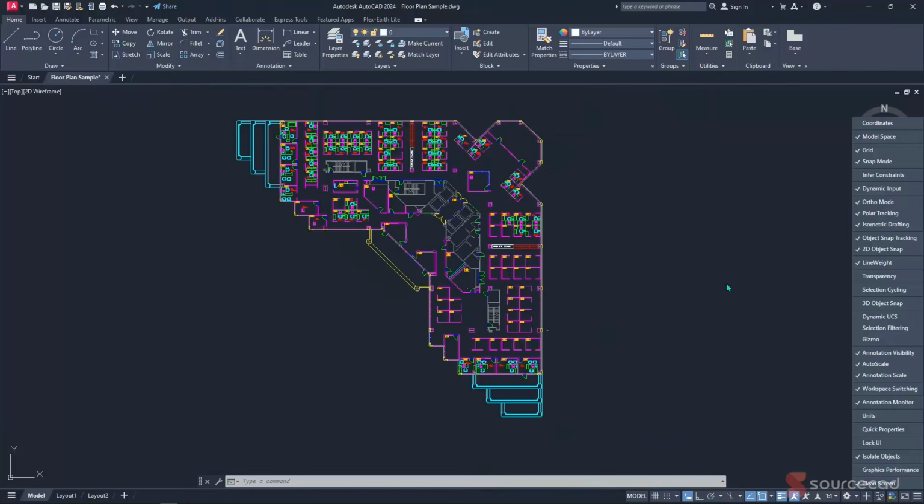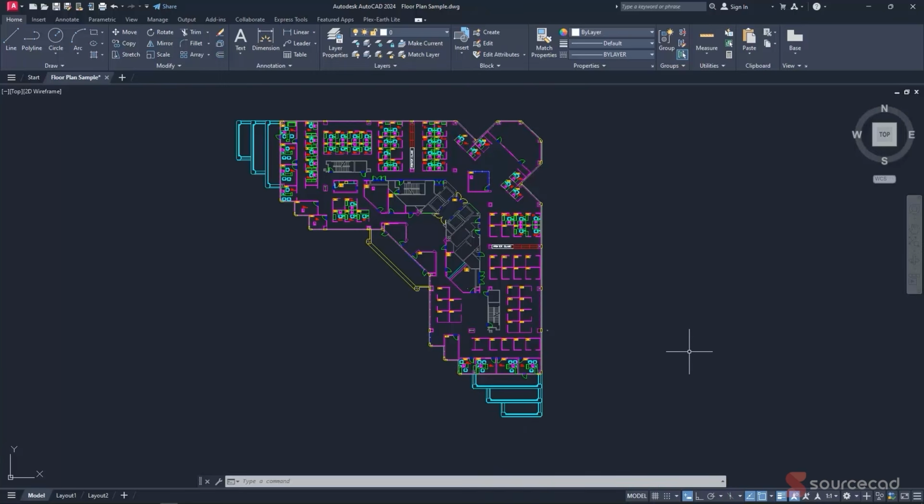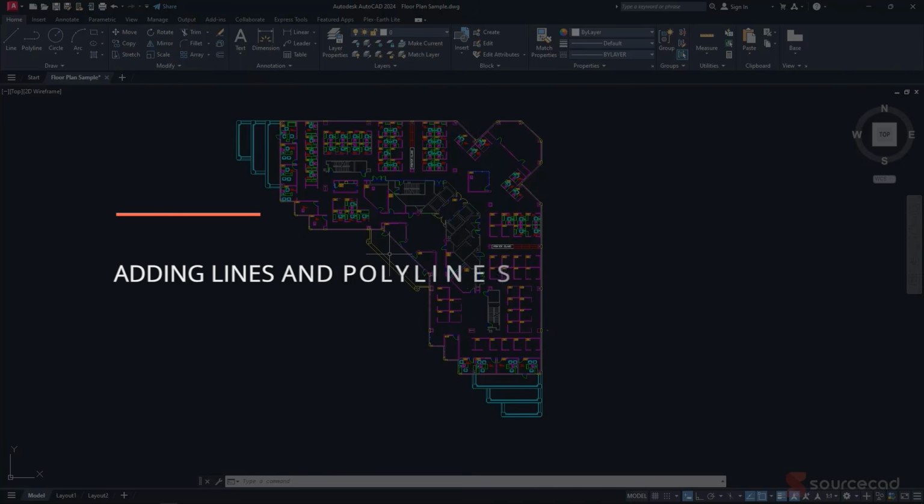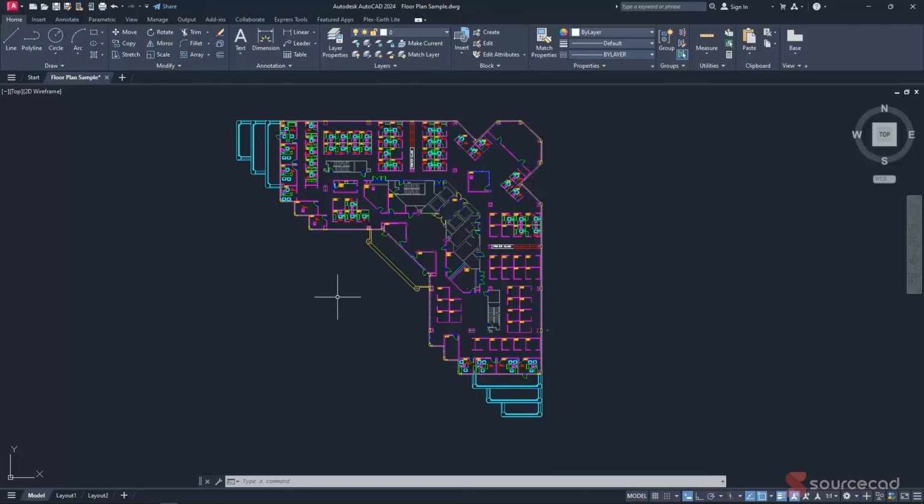Now back to learning AutoCAD for civil engineers. So having gone through that basic user interface layout, now we can simply see what we have in front of us. So if I actually wanted to create lines within our drawing, it's very easy. I can either opt to input a command, and for this case, it's actually L. So L is a command for line, and I hit enter and the command will be shown.